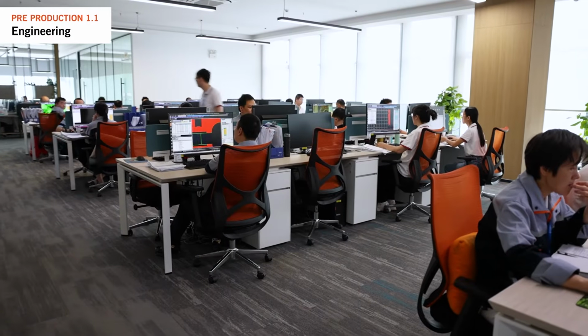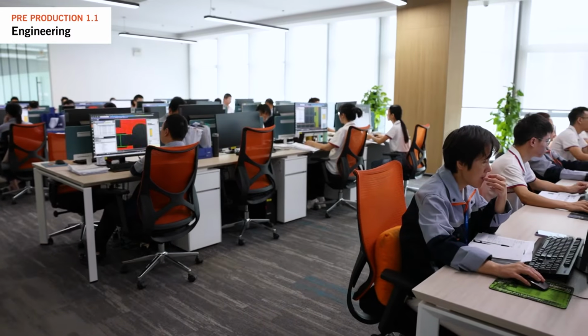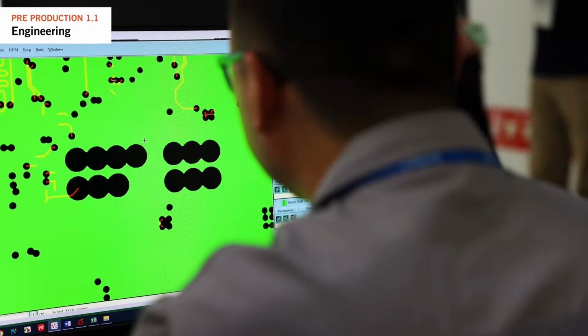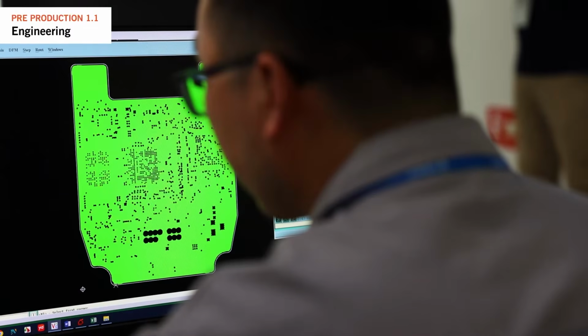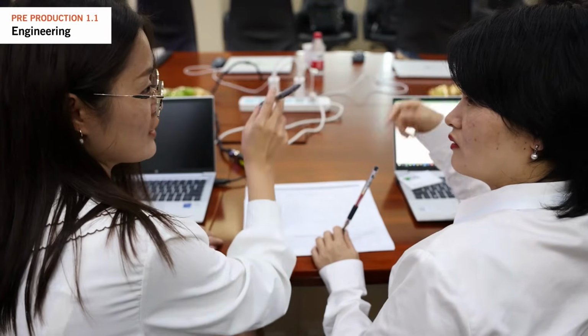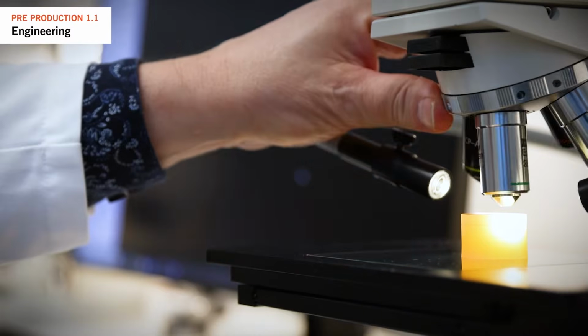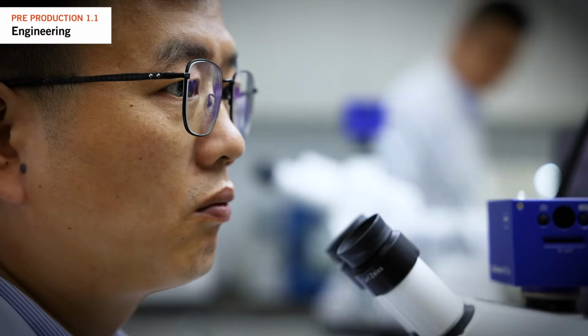This is a detailed and critical process. Its purpose is simple though, to take electronic data or Gerber data from the customer and generate the necessary tools and working files so the factory can build the PCB correctly. We also review any specific requirements and ensure that they're followed during production. Failure here can be carried into production and we can potentially build a perfectly wrong PCB.